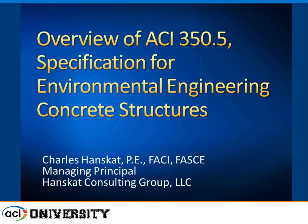When we first got into writing a code for ACI 350, we found that ASCE didn't have the information in ASCE 7 that we were really looking for, that we needed for design of liquid containing structures. So we actually developed the loading side that typically is left to ASCE 7 and put it in our own document. We maintain that document. Since then, ASCE 7 has actually picked up on many of the things that we put into 350.3. Then we have a 350.4 document that is kind of a guide to design of liquid containing structures. There's helpful hints on things that are needed when you're designing a liquid containing structure.